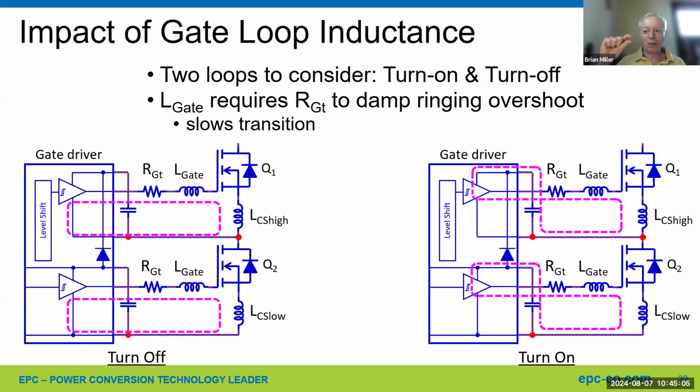A few answers to that. One is with a good gate drive, you won't have that kind of problem. If you can have a minimal loop and GaN FETs are small, then that won't be a problem. If it is, then the GaN threshold knee is not as sharp as it is with MOSFETs. So if you go into the threshold, which you shouldn't do, but if you do, it doesn't mean everything falls apart right there and it cross conducts and blows up. It means the leakage gets worse there for a bit.